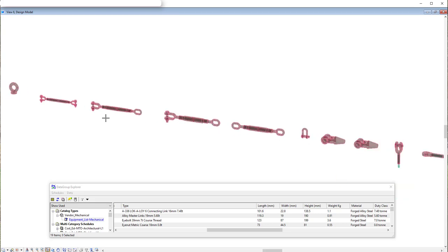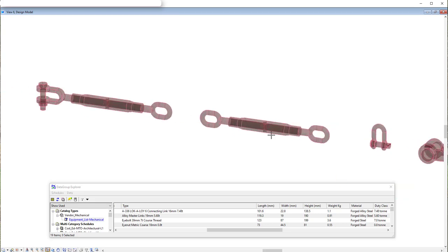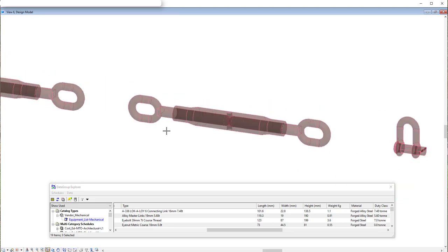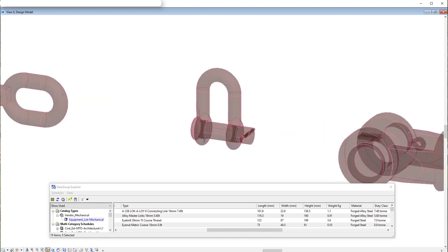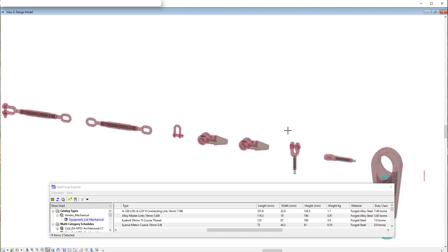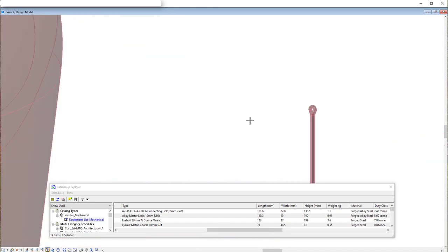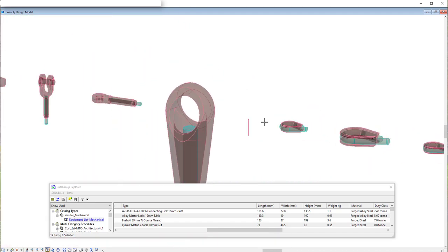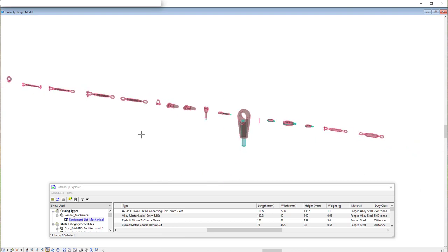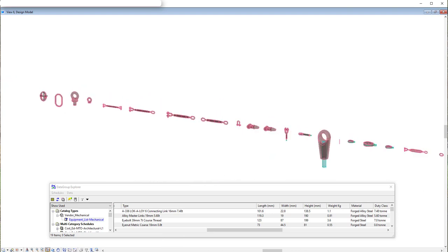And you can see here, it's got all the necessary details in there for all the interface, but without all the fancy fillets and engravings and everything else that comes with it. Typically, if there's a vendor model, it'll come with all those engravings and all that unnecessary detail that we don't need to show on the drawings, and we don't need it in our models.